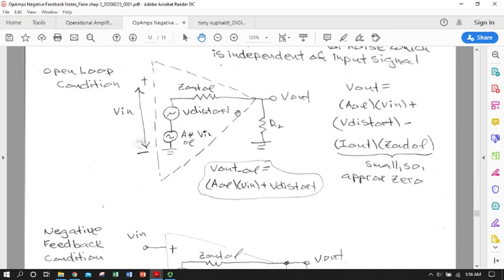We want only the signal that we care about. So that distortion could maybe be an offset that would cause us to read a thermocouple voltage wrong and assume we have a higher or lower temperature, or read an incorrect amplitude on a sinusoidal signal, something like that, and get the wrong information. So these are bad. It would be really great if we could make these go down.